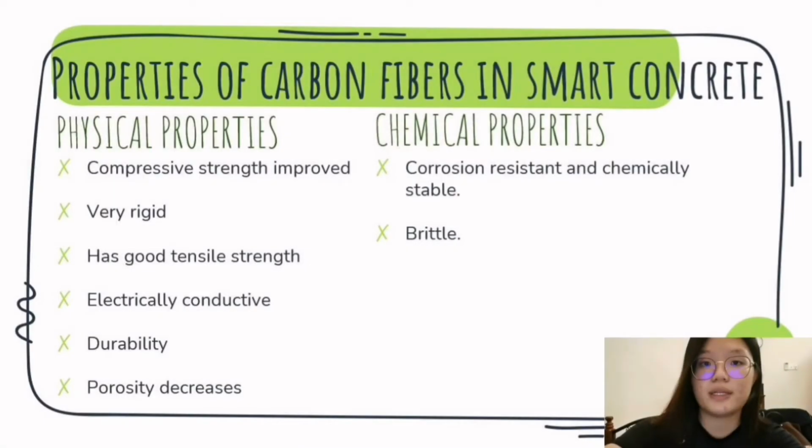For physical properties in smart concrete, the compressive strength and split tensile strength of concrete are all improved. Concrete becomes very rigid and it is electrically conductive because of the presence of carbon fibers. Carbon fibers also increase concrete durability and decrease its porosity.